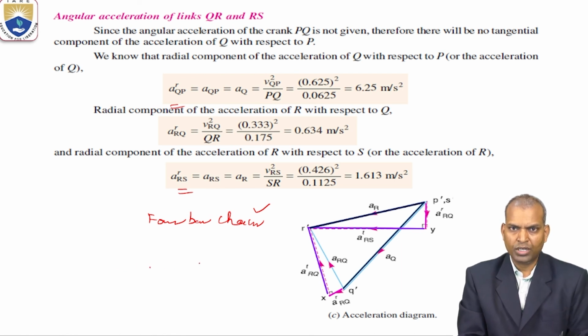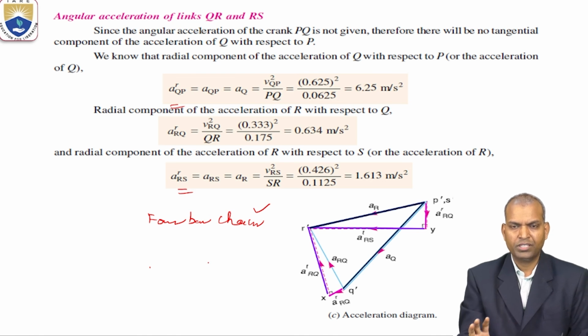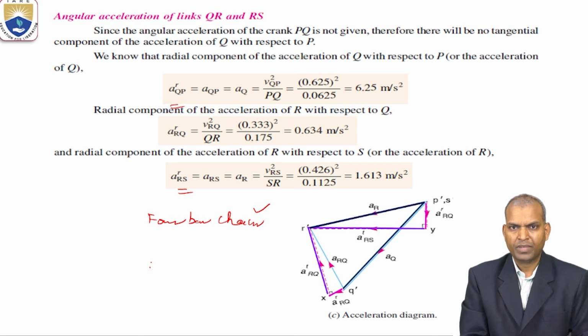Beside that, you have to draw either on the left side or right side, either top or bottom, in such a way that you can use either set squares or a mini drafter. You have to draw the velocity diagram beside it. It can be away also, but you need a set square, and the size of the set square required is larger. Similarly, the acceleration diagram should be beside the velocity diagram or beside the configuration or space diagram.